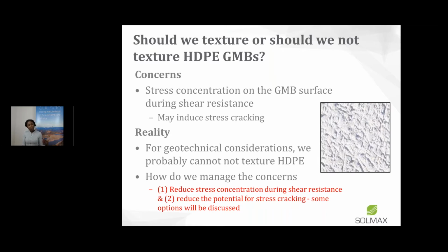So when he asked if I was going to make that statement, I thought about it, and I thought, he has a good point, but in reality, given all the things that can happen on the site with your interface friction angle, for geotechnical considerations, I don't think it's possible that we don't texture HDPE geomembrane, right? What I think is that we shouldn't be looking at not texturing HDPE. What we should be looking at is how to manage the risk associated with texturing HDPE.